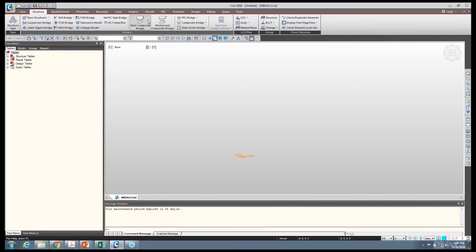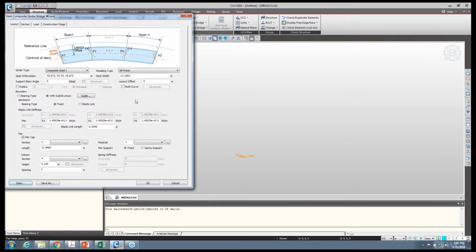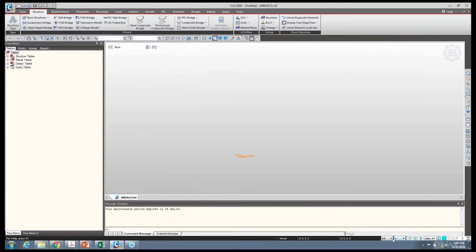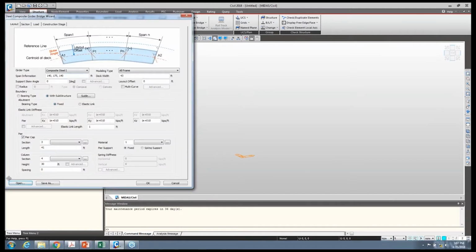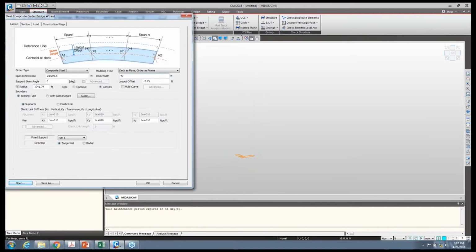Hopefully, through the course of this presentation, everyone takes away the following items. One, I hope that MIDAS has the ability to provide analysis for multiple structure types. Due to this capacity, there are a lot of buttons and design modules that can make this program a little bit intimidating. Similar to other design software, there is always an easier way to modify models to make things easier for the user. So hopefully by showing the versatility of using the wizard input and the MCT shell command, which is a little text input, we can reduce the modeling time for some of these unique structures, or at the very least reduce stress injuries caused by multiple mouse clicks.